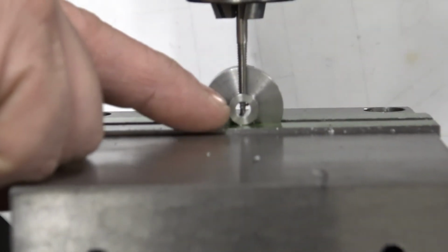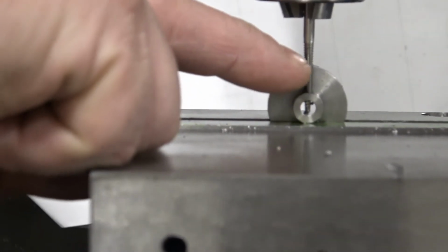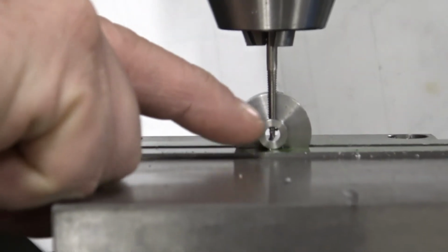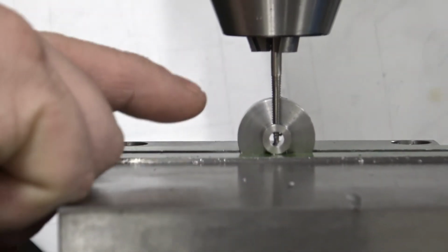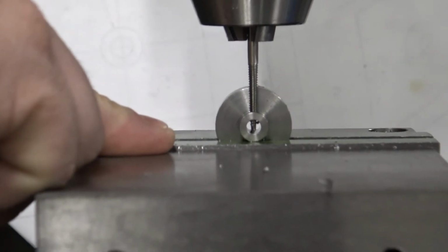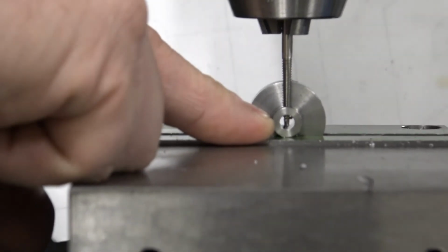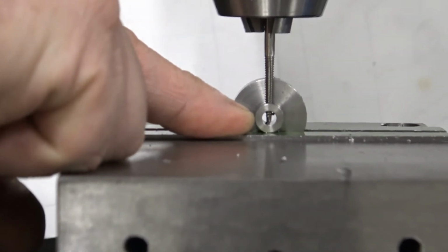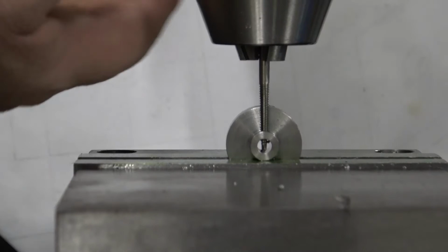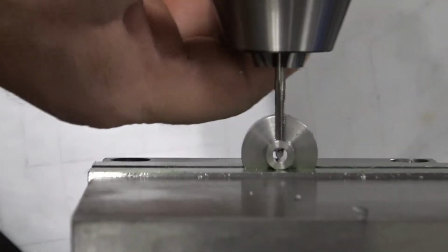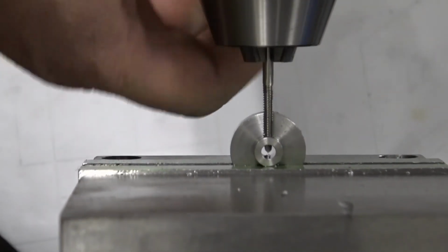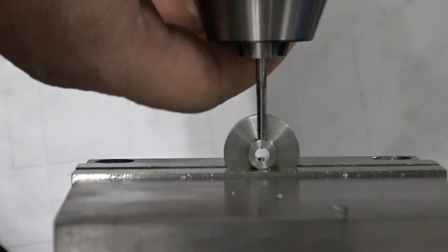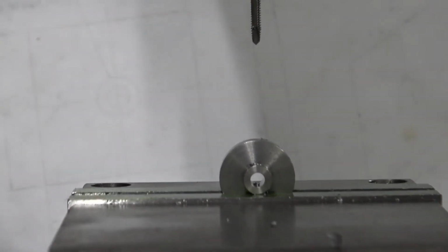So as you can see through that center hole, the very tip of that tap is touching the other side of the hole that it goes through. That's as deep as you want to go. If you try to drive the tap past that, you're going to start putting a lot of load on the threads and potentially cause that tap to break. So once I get that far, I'm going to turn the spindle in a reverse rotation, which is counterclockwise as I'm looking at the top. And when it frees up from the thread, it's going to release itself.